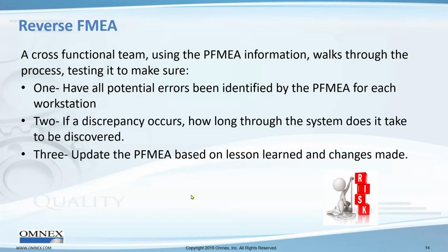And we'd want to make sure that in relation to the control plan, the plant is following the control plan. So on the control plan, it says they're supposed to be taking 5 samples per hour and plotting those on a control chart. We should see that's what they're doing, and they're following what's in the control plan. So as we go through it too, we may find discrepancies.